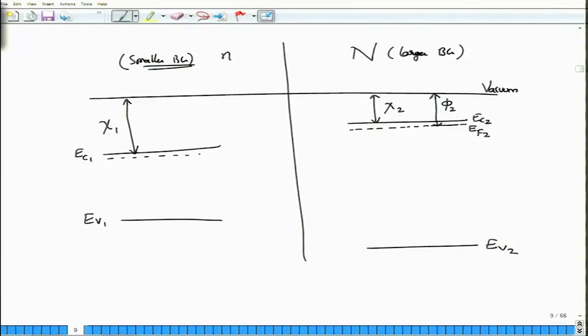As before, the Fermi level has to be found near the conduction band, therefore, this is located close to the conduction band as it is. So, this is a junction far away from whatever is happening. But at the junction itself, sometimes also called the metallurgical junction, what really happens? This is an n-type material, capital N, but it is still nevertheless an n-type material. Therefore, even when you merge these two materials together, the overall characteristic should still be an n-type material characteristic.